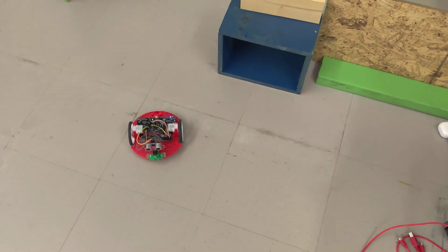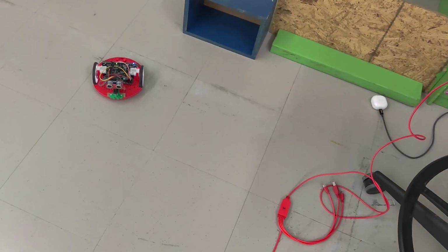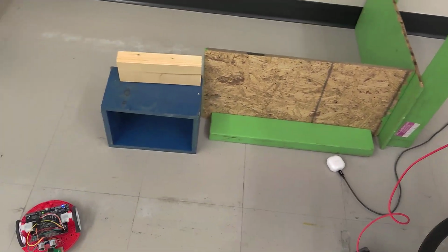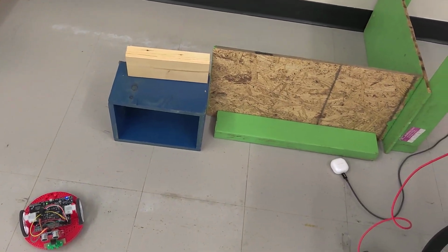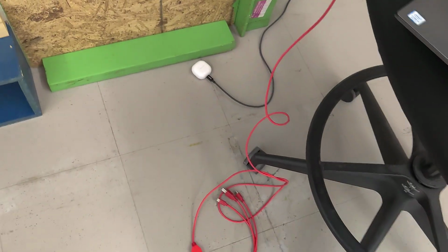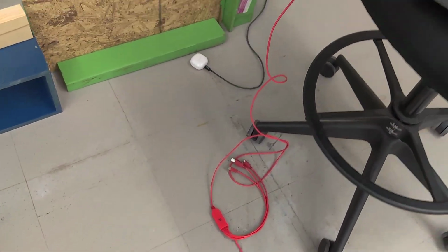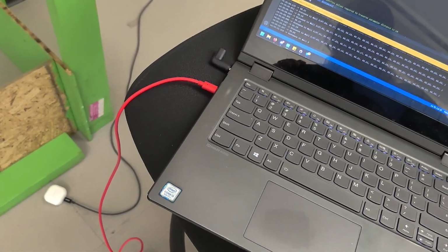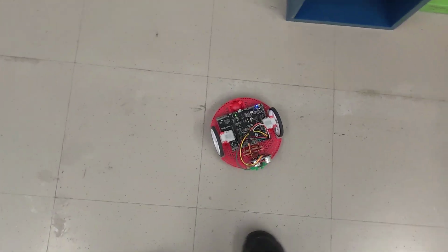Because there's open area here, it's going to grab a bunch of non-measurements, or 4 meters and plus. That gets filtered out, comes back into my array as 0. And so min won't grab any of that. And then if it hits any of this stuff over here, that's fine too. It's going to be less than 40 in case it hits, for it to be assigned as min. And once it knows for sure that that 40 centimeter area is clear, it's going to go ahead and turn that green LED on and be ready for another run.